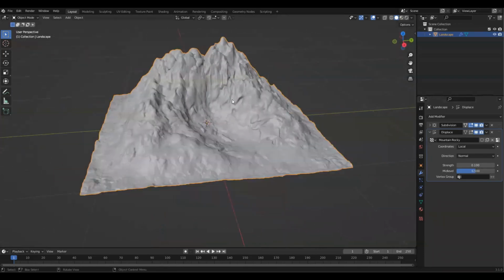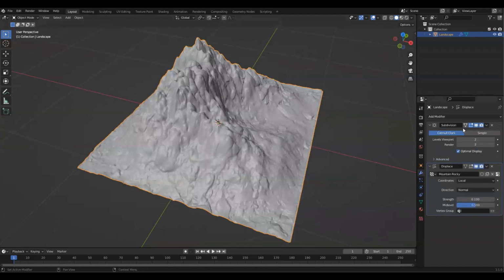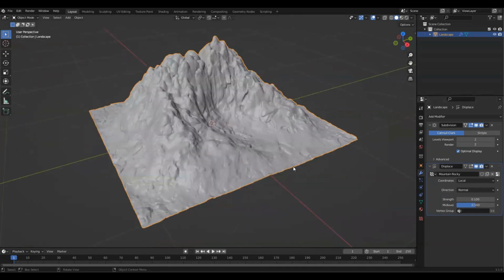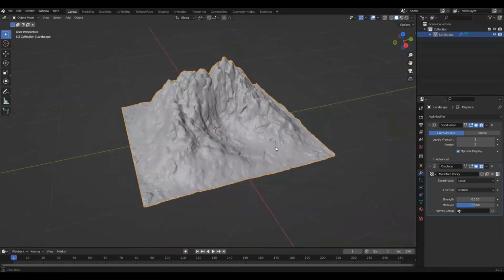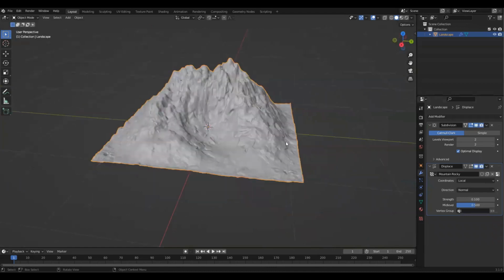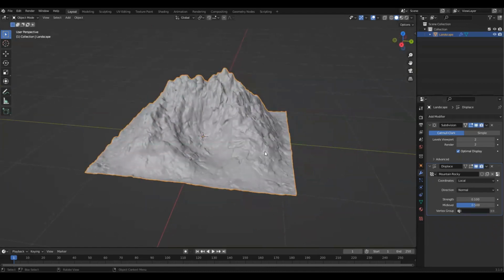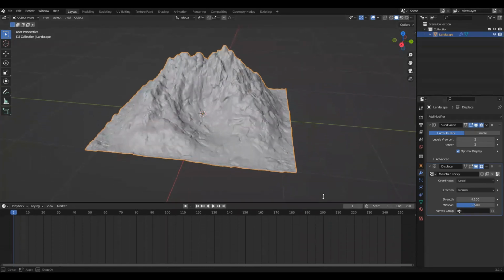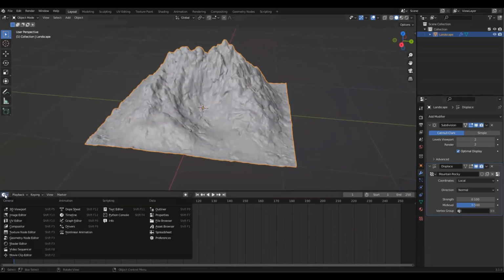And so now we had that base mesh. We added some detail potential with the subdivision, and then we added in an actual displacement map for that final level of detail. So that's the base mesh we're going to work with. And let's talk about how to set up a material of some kind that looks somewhat realistic. So let's unfurl this menu down here a little bit further and change that over to the shader editor.